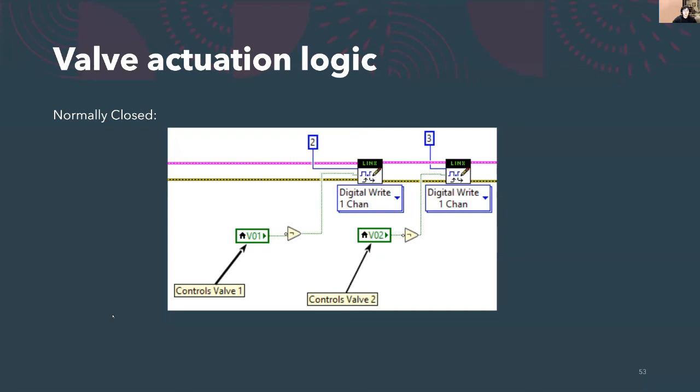Because of how the relay board works and the valve actuates, if the button is not pressed, we want the valve to be closed, but this causes an issue. Because the valve is normally closed and the button is not pressed, this creates a logical 0 as an output. This would then activate the relay, which energizes the circuit and would in turn open the valve. To combat this, the NOT gate is added so that when the button is in the off position, the system will output a 1 and keep the valve in the closed position.